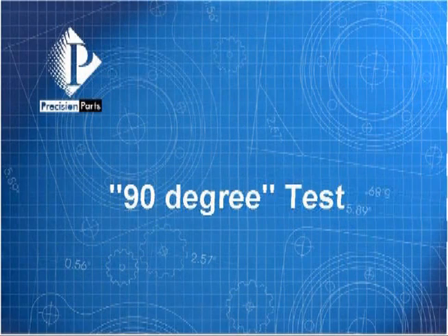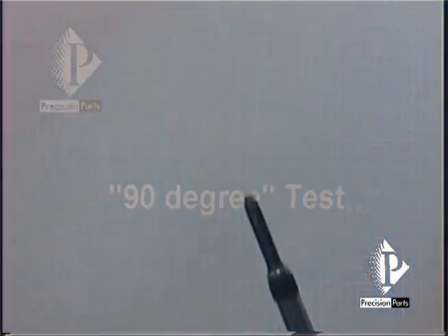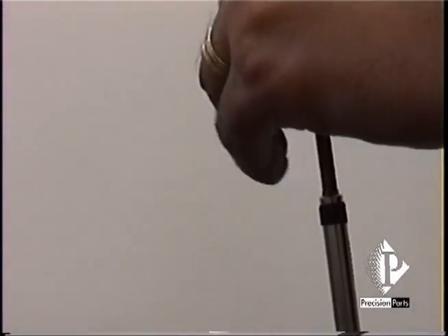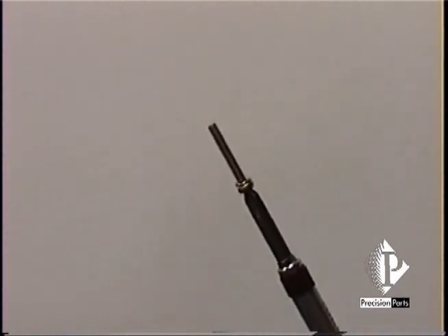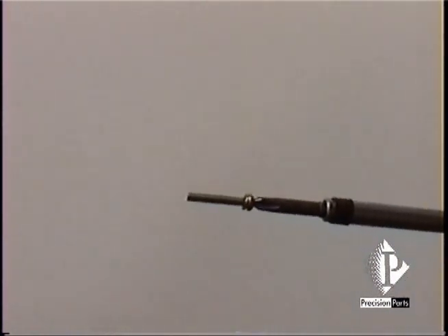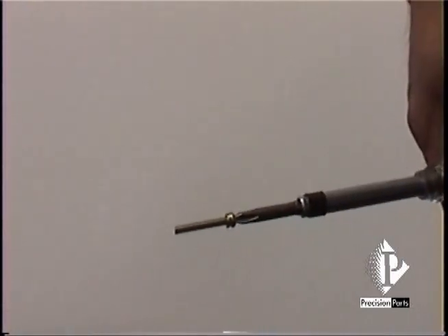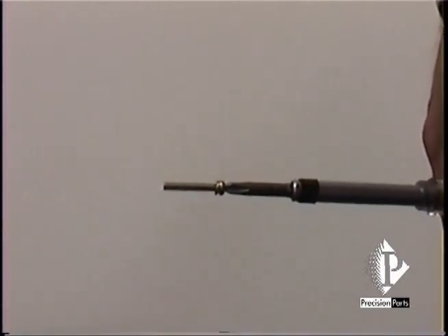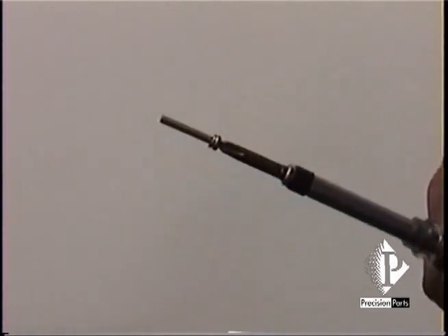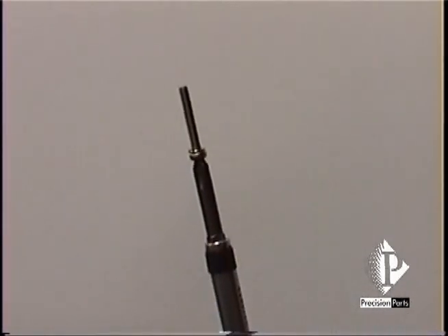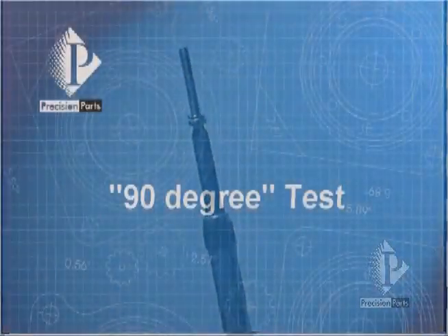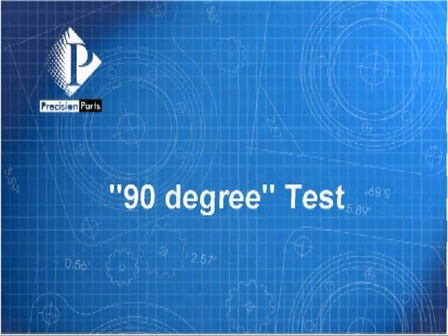When you have a Phillips or posi bit in good condition, there is a test that you can perform to verify that you are using the proper type of screw. To perform this test, place the screw onto the screwdriver. Now, turn the screwdriver so that it is parallel to the ground. If the screw is of the proper type, it will not fall off. Be aware that the screw will fall off if the screw or the drill bit is worn. Be sure to perform this test to determine if you are using the right screw and the right screwdriver.